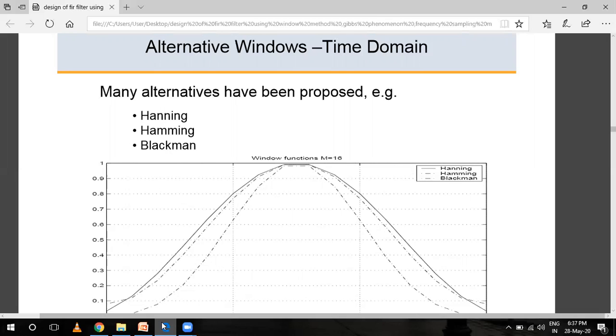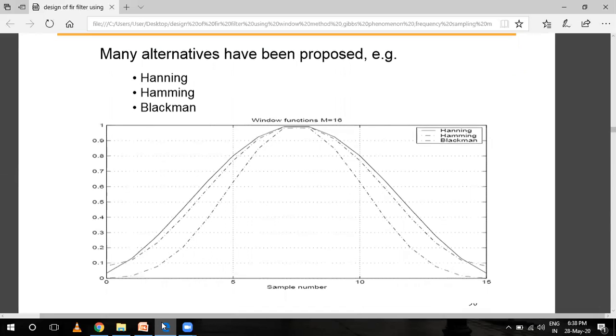The purpose of the windowing function in FFT is that it enhances the ability of the FFT to extract spectral data from signals, and reduces leakage, where spectral information from the FFT shows up at the wrong frequency.